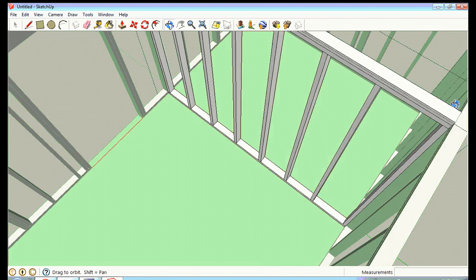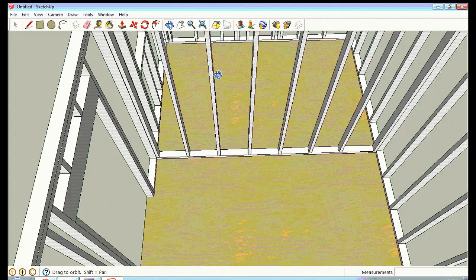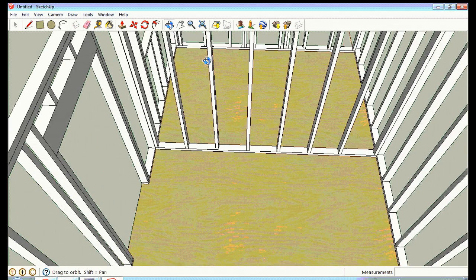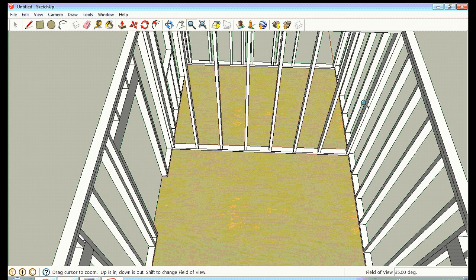Now there's your interior wall, and of course you're going to want a door unless you're creating a prison cell. You better put a door in your interior wall here. So wherever you want a door, you just follow the same thing that we did for the outside walls. Now I would put a 2x4 stud like I did over here against this other wall over here too, because you need two of them to nail those two. But to save time, I'm not going to show you doing both of them because you see how it's done.